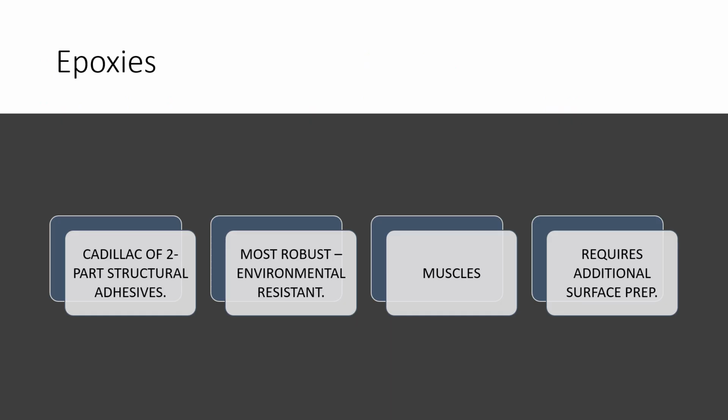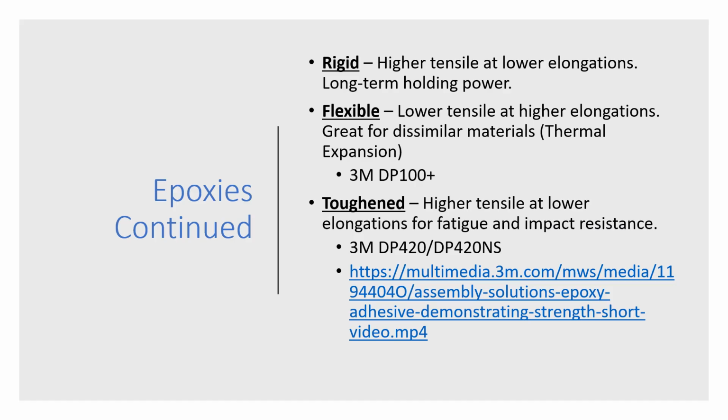Like I said, epoxies are the Cadillac of the two-part structural adhesives, the original structural adhesive: most robust, strongest, best with environmental resistance. Think of them as the muscles. They do require additional surface prep. 3M has 3 different families of structural adhesives in the epoxy lineup.